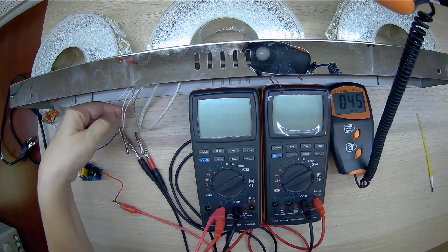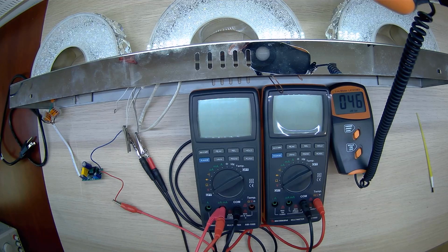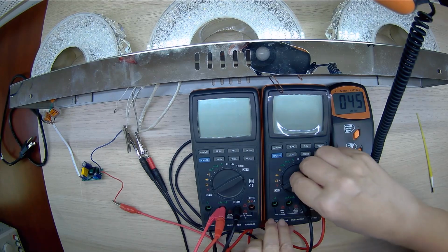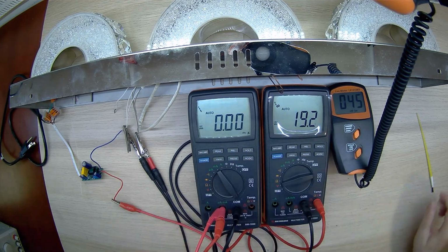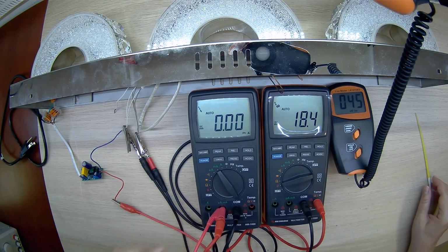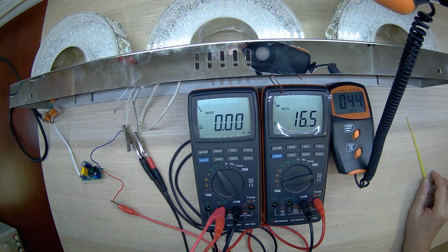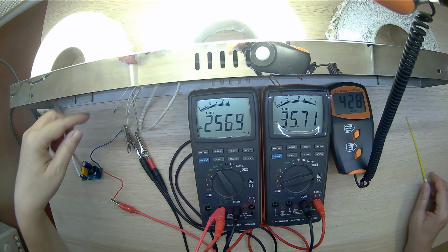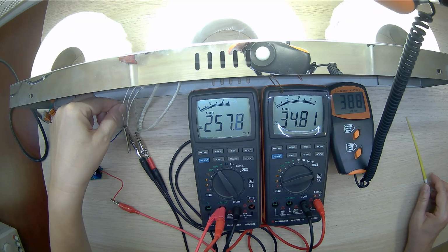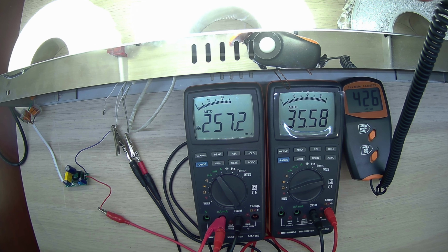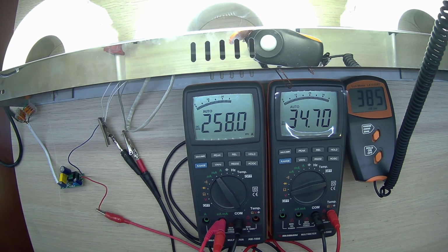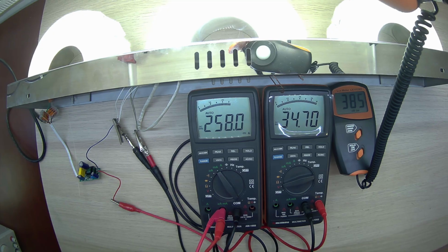First, let's check that the new driver is working and all sections are in good condition. To do this, we'll connect 2 sections to the new driver so as not to exceed the current of 200 mA per section and measure the brightness. We turn on multimeters and external voltage. Obviously, the brightness of each section is less than nominal. We connect all 3 sections and see that all sections are working properly. And our assumption at the beginning about the driver malfunction is correct. Here we see that the driver current for LED is 257 mA.